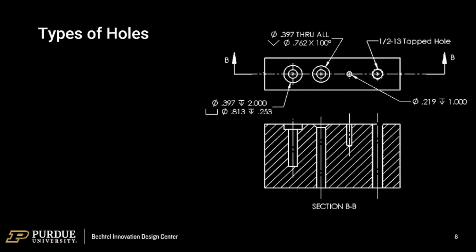So here's a top and a side section view of 4 different types of holes with representative callouts. As we talked about earlier, please don't specify that flat-bottomed hole unless you have an absolutely good engineering reason to do a flat-bottom hole. Otherwise, do a drill point hole, like the 3rd one there, or a through hole.